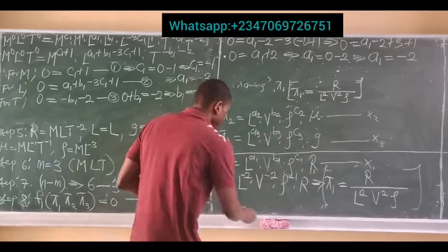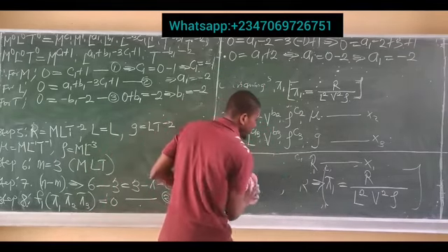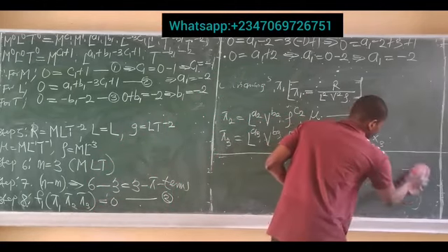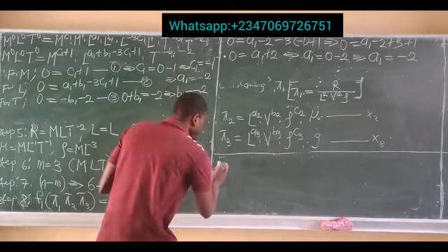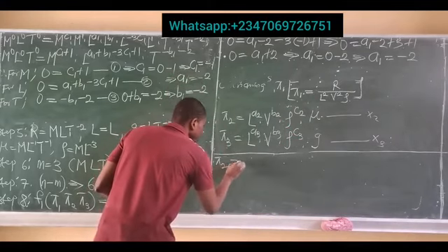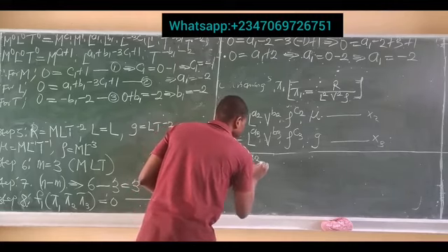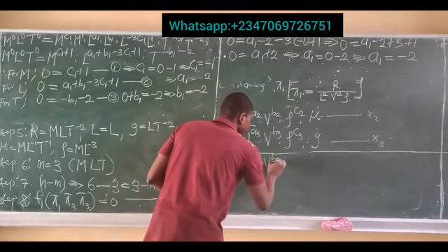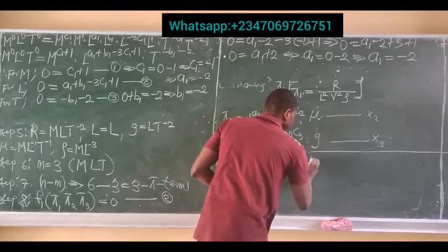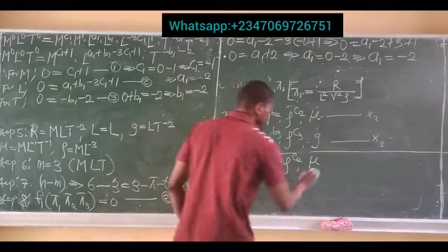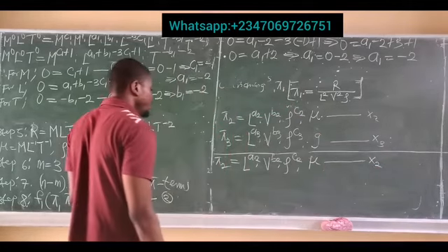All right, so we can take this off now. Then we start with pi2, doing the same thing that we've done, applying the principle of dimensional homogeneity to solve for pi2. Now, what is pi2? Pi2 is equal to L to the power of A2 times V to the power of B2 times rho to the power of C2 times mu, which is dynamic viscosity. This is equation X2.